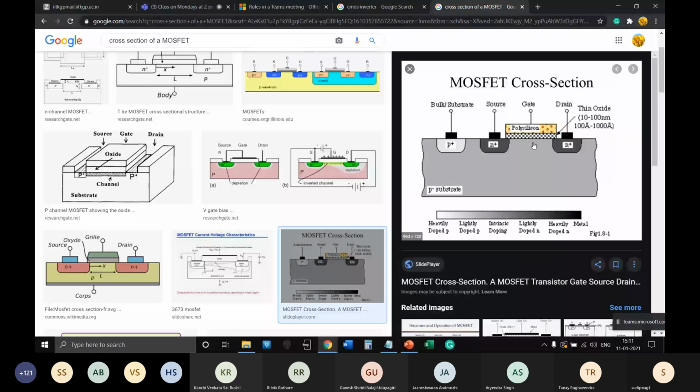Now, coming to the question, if I connect bulk or substrate to the drain, and the drain is typically at a larger voltage for NMOS transistors, then this junction will get forward biased. Instead of leakage, the junction formed over here will start taking some current. So now P plus will get a positive voltage. The drain has a larger voltage, the source has ground voltage or 0 volt in our existing schematic.